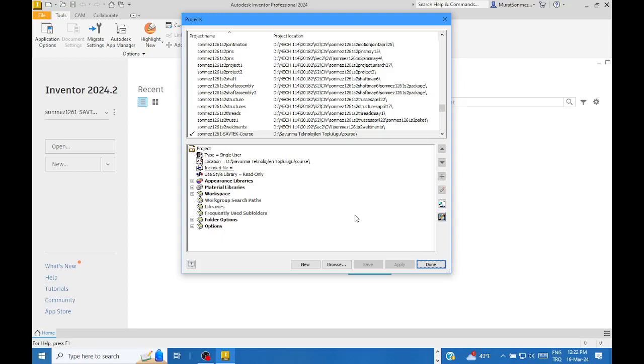The main advantage of being in an active project is that the process is going to be applicable, and also you can ensure that all the files, the log files in which Inventor keeps the results of calculations, are going to be at the same address. No need to search which file is in which address.